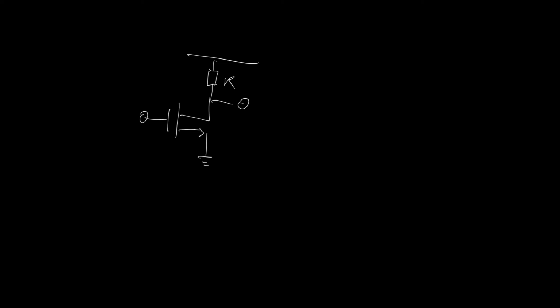In an earlier video, we explained that this simple circuit with an N-channel MOSFET down here and a pull-up resistor here functions as an inverter. However, having a resistor here is not a good idea. Basically, we want R to be large under some circumstances, and we want R to be small under other circumstances, and thus no value of R is going to be a good choice.